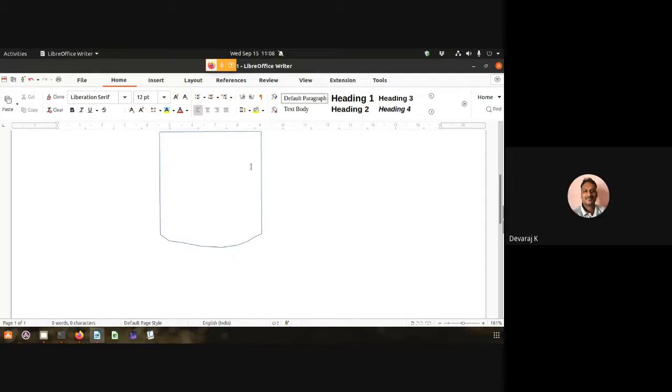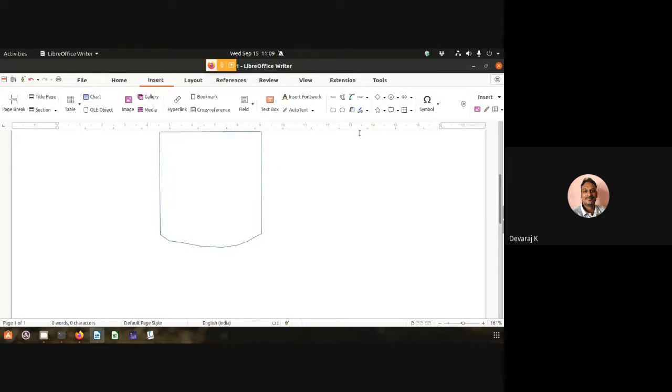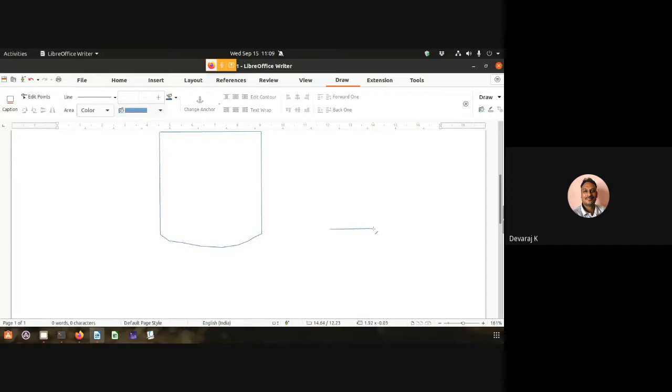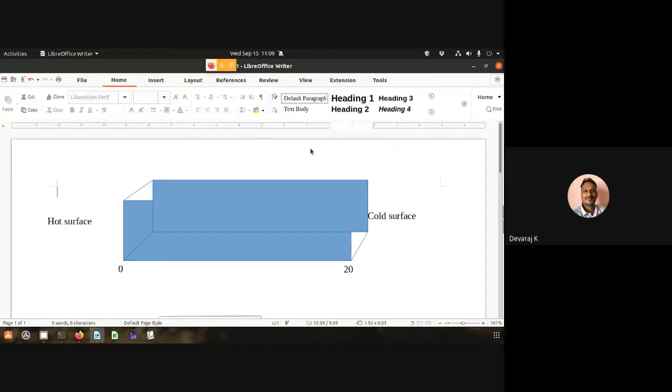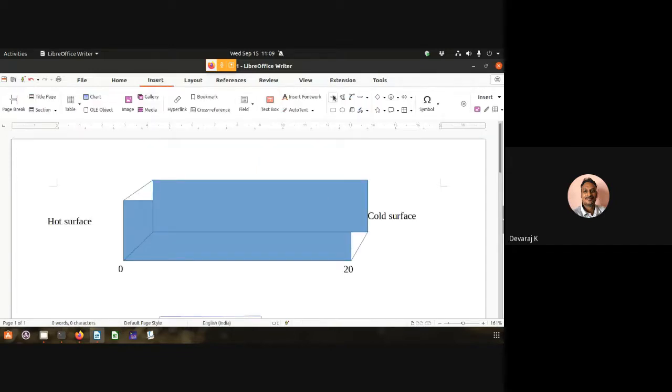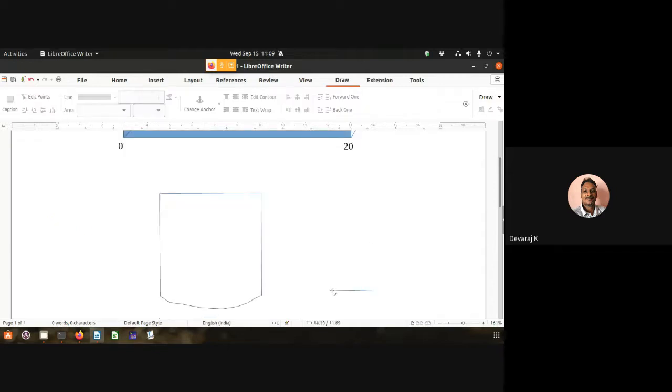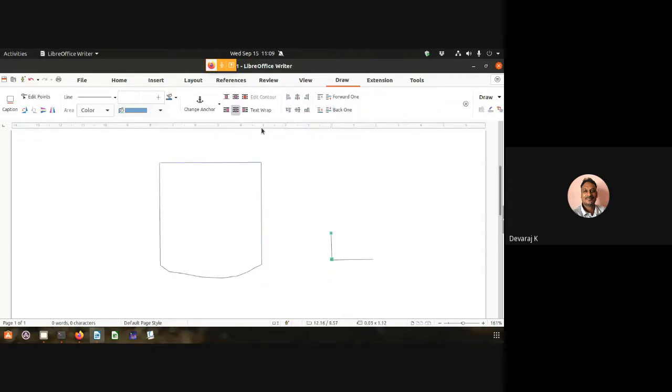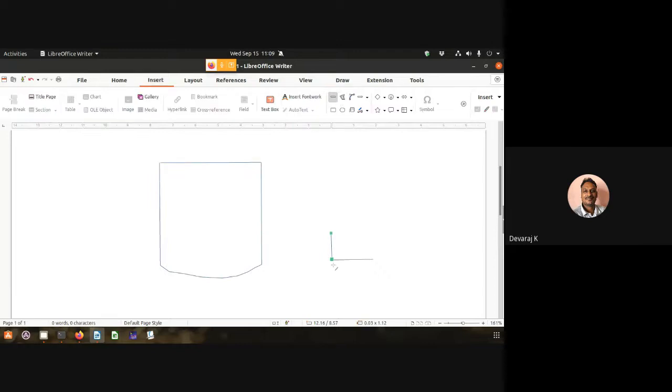You have this particular thing, I have to define the vertices. So what I'm going to do is the same thing, but here I'm going to use the feature that is there in blockMesh, the arc feature. So this is my x direction, and across it the y direction, and you have your z direction.